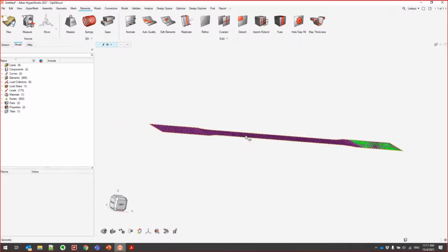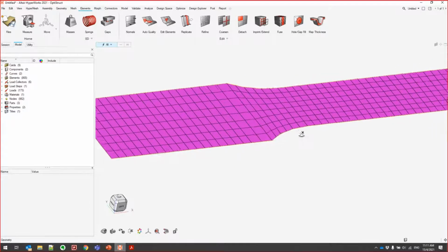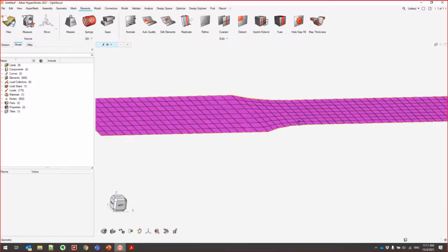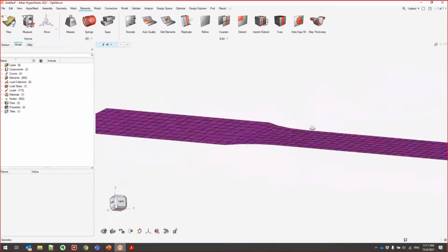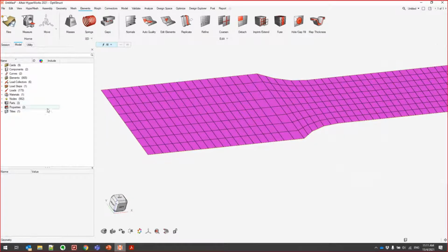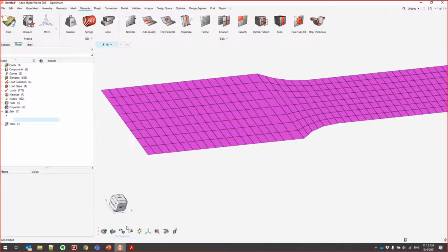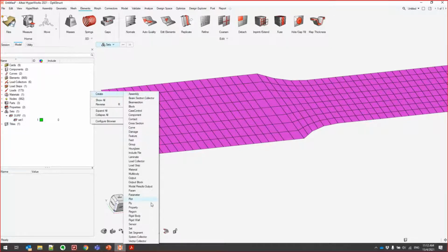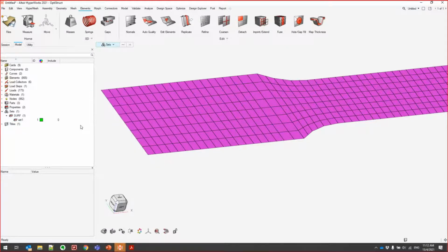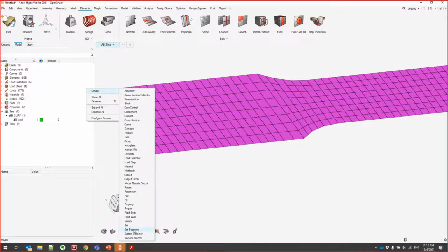So imagine, just now your question, you have a shell element. You're going to generate contact for both top and bottom, right? So imagine this, I generate a contact now. I create a set segment. Okay, so don't ask why we call this set segment. It should be called surface. Right, so if you need to create a contact surface, you right click, create set segments.